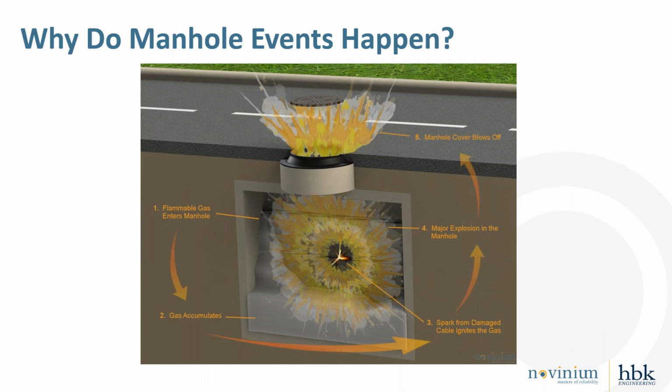These events are a combination of actions that occur in our underground electric infrastructure. The typical event is a combination of load changes in our cable networks that lead to cracking due to thermal cycling. When coupling cracking with the conductive medium, in this case salt, it breaks down the cable further, but also provides an avenue for electrical tracking, or in this case arcing. While the cable is breaking down, various gases are formed within the conduits and open spaces underground in our electrical systems. The arcing combined with the gases lead to these events of smoking, fire, and explosions in varying degree.